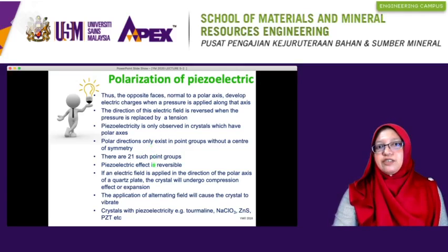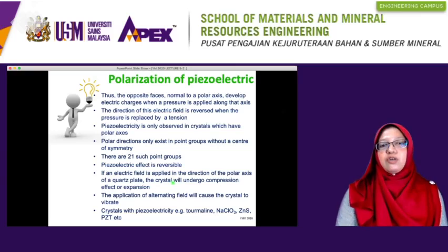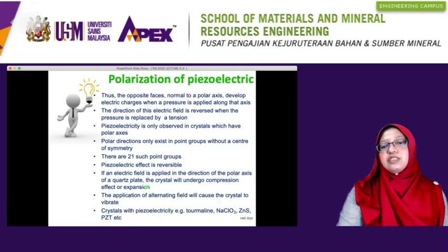The piezoelectric effect is reversible. If an electric field is applied in the direction of the polar axis of a quartz plate, for instance, the crystal will undergo compression or expansion. The application of an alternating field will cause the crystal to vibrate, and crystals with piezoelectricity, or piezoelectric materials, include tourmaline, ZnS, and PZT.